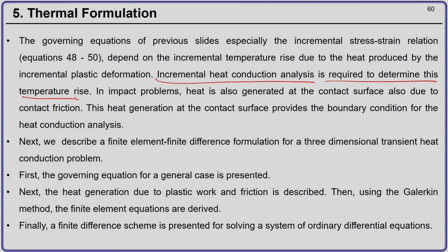Now, in impact problem, you will have heat which is generated at the contact surface because of the contact friction. In elastoplastic problem, you also have heat generated because of the incremental plastic deformation. So, now you have two different ways in which the heat is generated in the system.